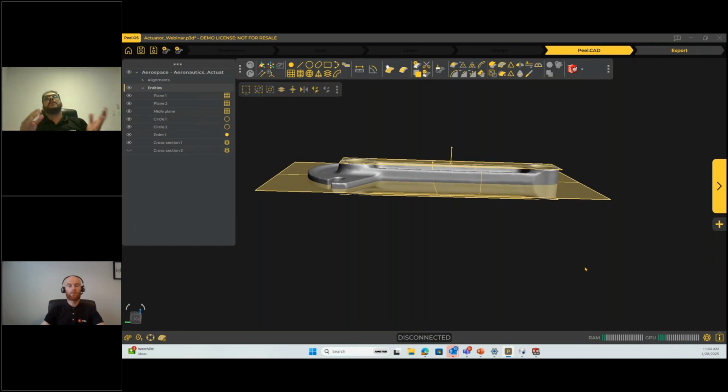If the hole is on a flat plane with nothing around it that the two cameras can't see, I think it will be something about 2 or 3 millimeters inside of the hole. But if you have a small hole of 3 millimeters, then you can add a pin in the hole, and instead of scanning the hole, you scan the pin. That's going to give you as well the center point of the hole.